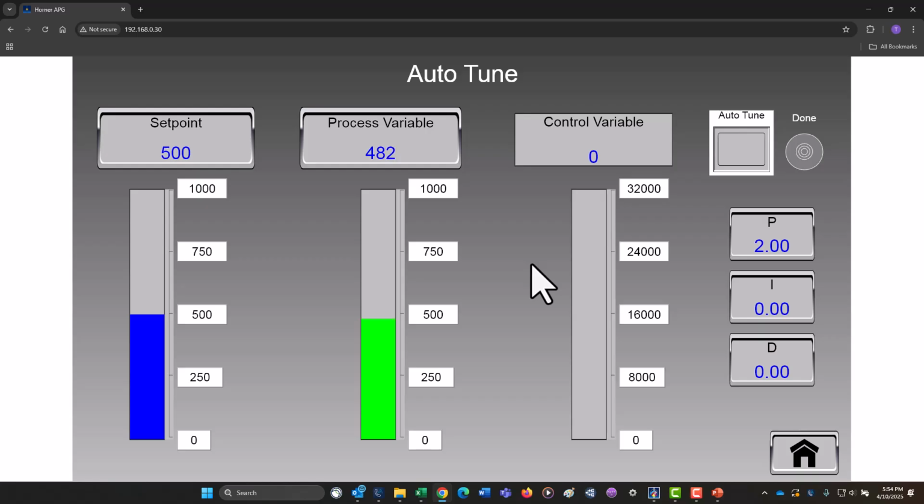And we had just completed one cycle, so we got 2 more cycles to go. Control variable is all the way up, so the process variable starts going up. We get far enough past the set point, now it goes down to 0. The process variable starts to come down. We repeat the cycle. Now we just finished 2 cycles, one more to go.